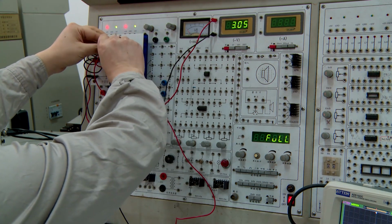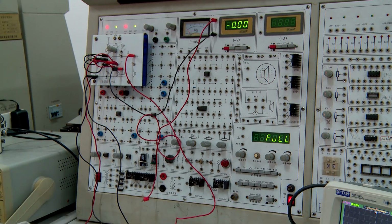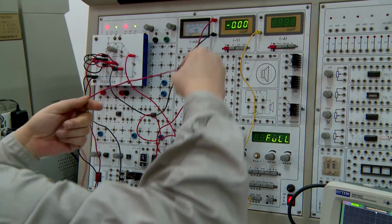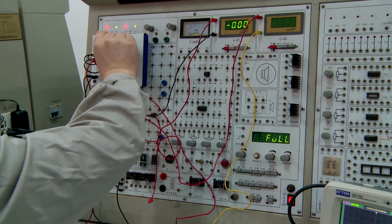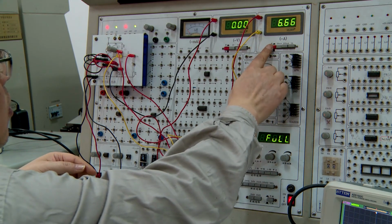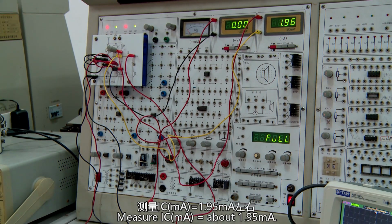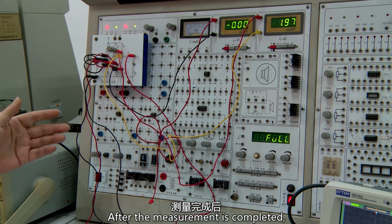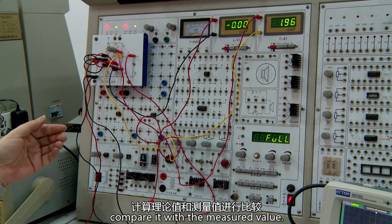Disconnect hole 7 and connect a digital direct current ammeter. Measure IC, about 1.95 mA, and record it in the table. After the measurement is completed, calculate the theoretical value and compare it with the measured value.